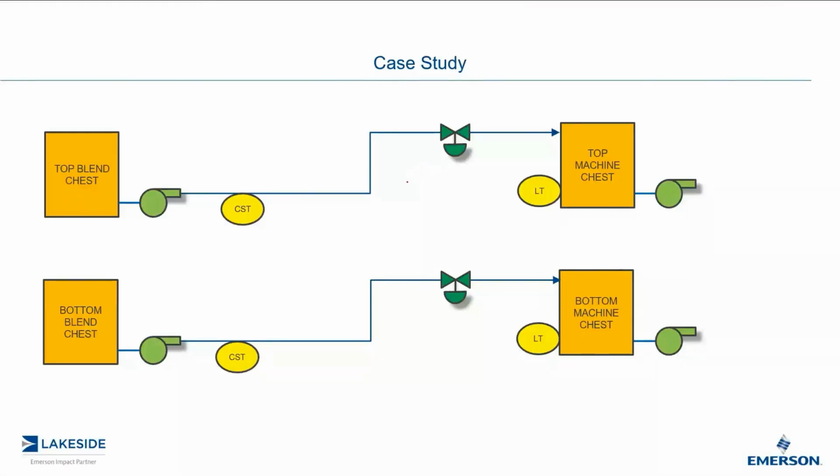So how do we use power spectrum? How do I use power spectrum? To be able to track down the source of variabilities. I did this towards the end of last year, working on a paper machine at a recycled paper mill. Recycling paper mills take your blue box paper and everything else, sort it out, put it through a pulper, break it back into fiber, and make a pulp slurry called paper stock.